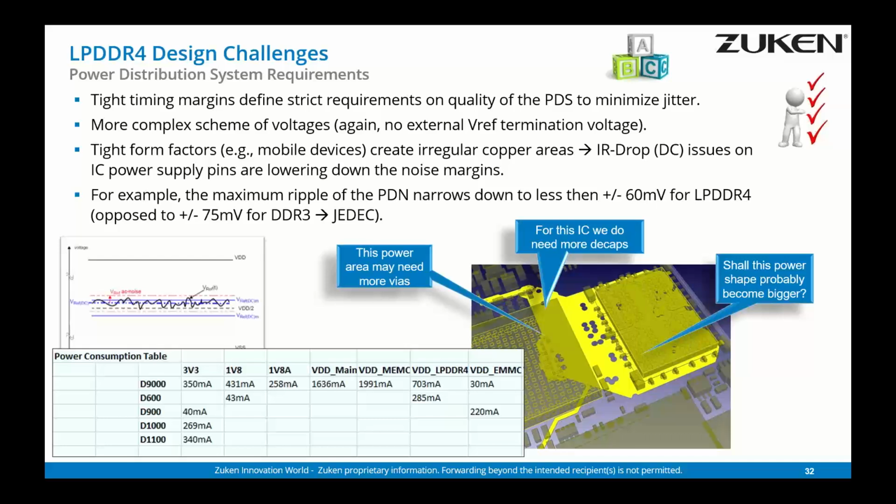And we have different questions which may occur pretty late in the process, like: do I probably need additional wires over here because of all the currents? What about the decoupling capacitors? Are the 5, to say a number, enough, or do I need some additional ones? Probably I have to reshape this copper area here to cope with some resonance or some IR drop. What is the current over here? All these are questions typically yielding reiteration cycles, and these are all power integrity related questions.